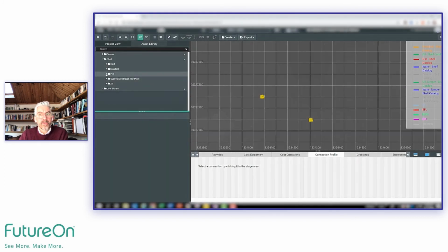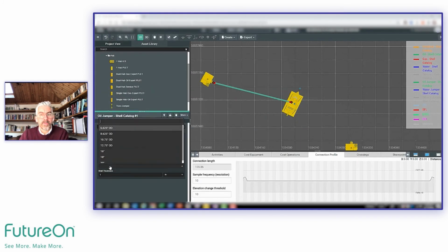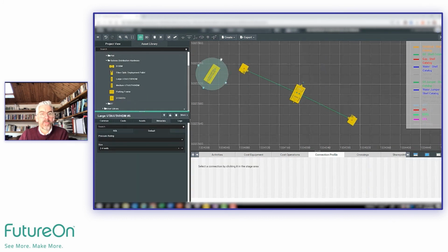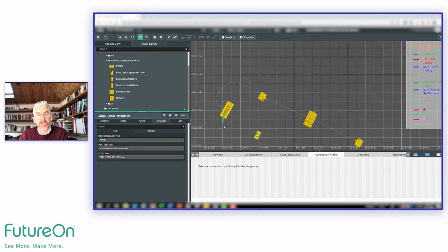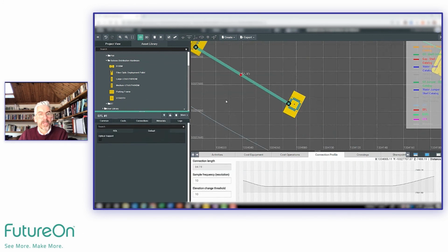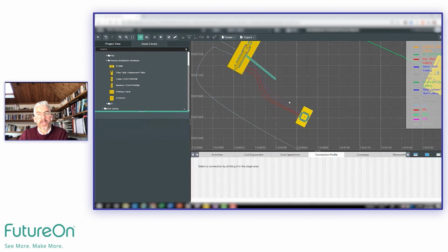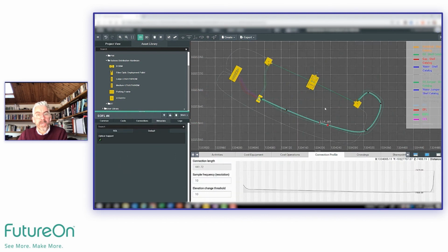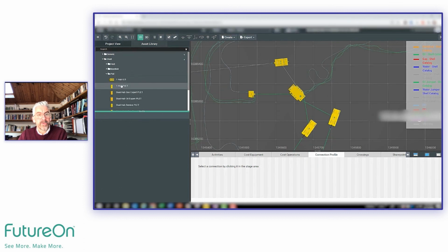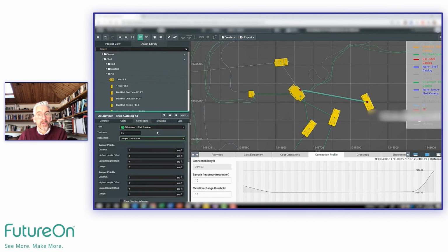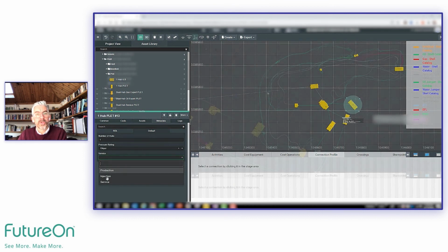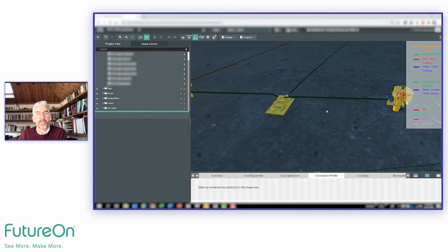This video is rather quick, but it shows the user within the FutureOn platform creating a new subsea field development. Here we're placing subsea equipment such as Christmas trees, manifolds, and pipeline end terminations, and then connecting them with jumpers, adding flying leads, and including bathymetry information for the seabed. All the equipment is geopositioned, ensuring an accurate production model and digital twin is available to users.